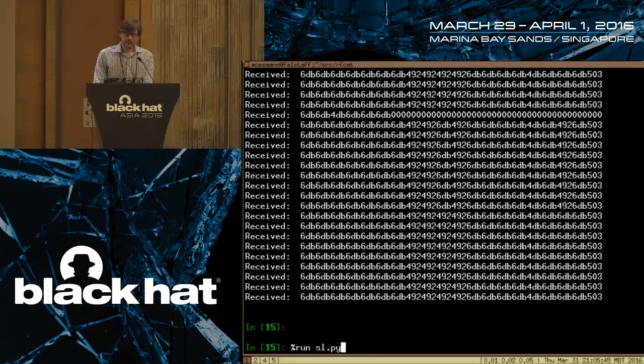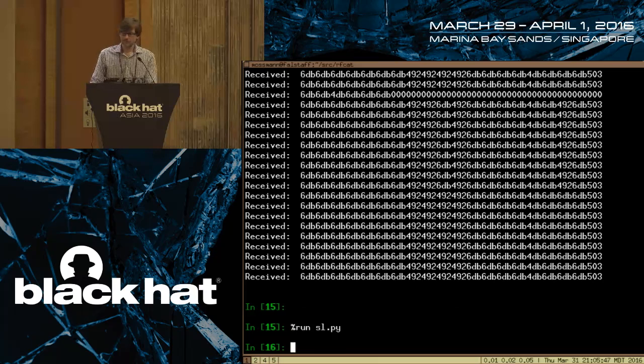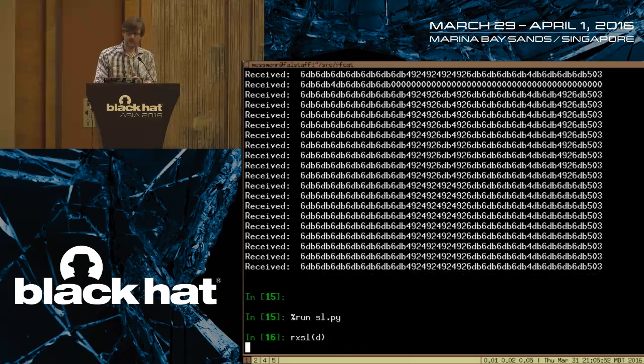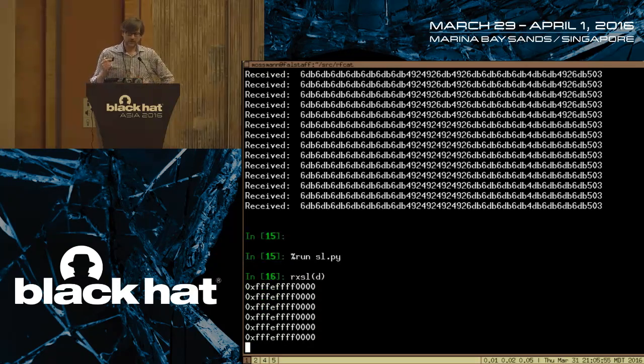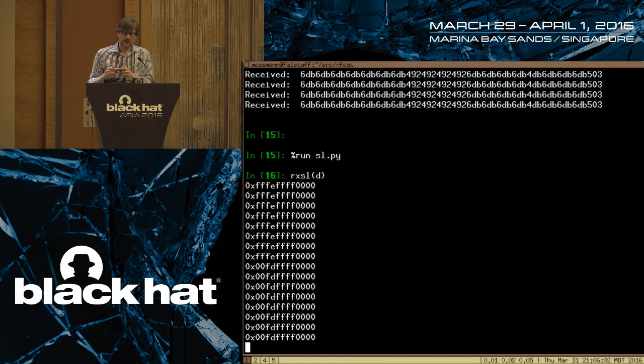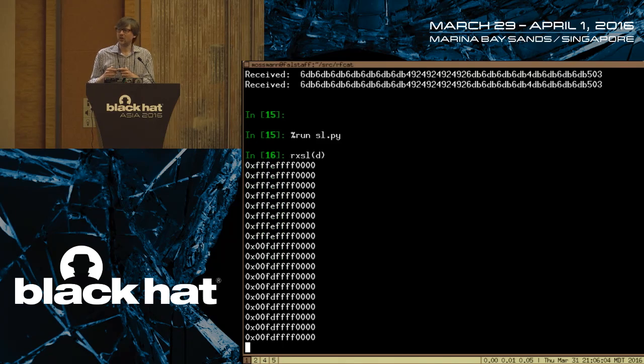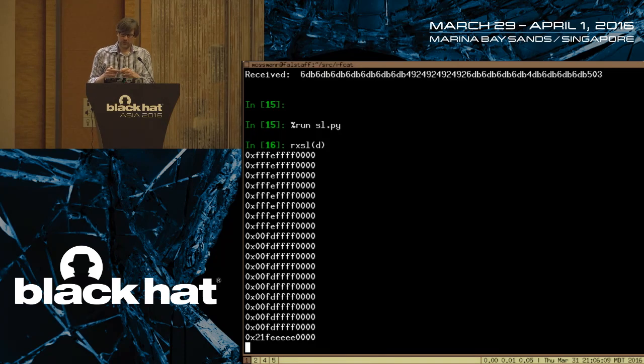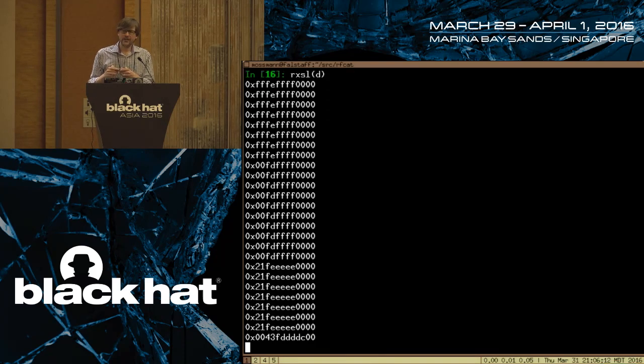If I load this, I can do 0, 0, 0, 0. Oops, I have to start my receive function. Lock. There we go. This is what it looks like if I'm just taking every 3rd bit. 0, 0, 0, 0, unlock. Aha. You can see only certain parts of the packet changed, right? What about 1, 1, 1, 1, lock? When I entered 0s, I got Fs, and when I entered 1s, I got Es, which tells me I probably have things inverted.